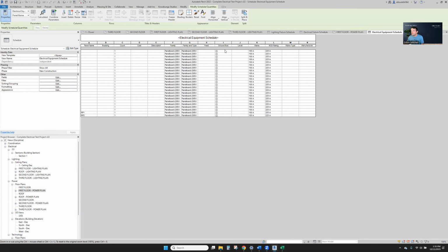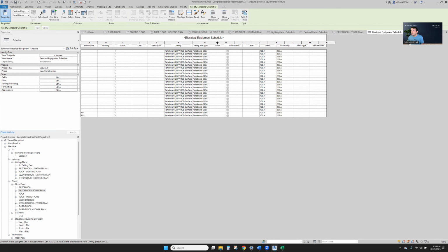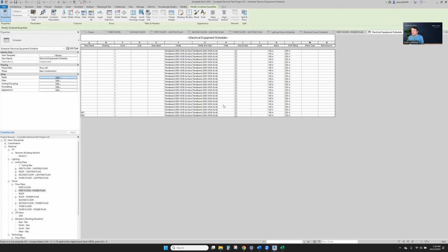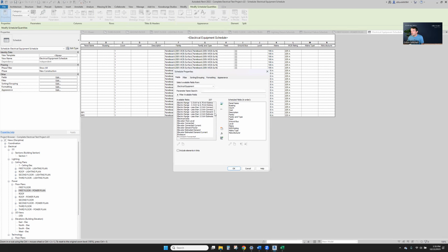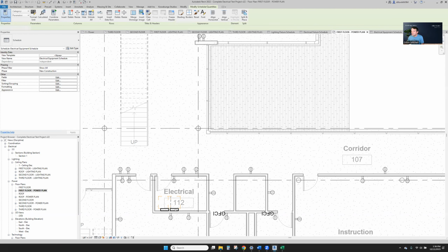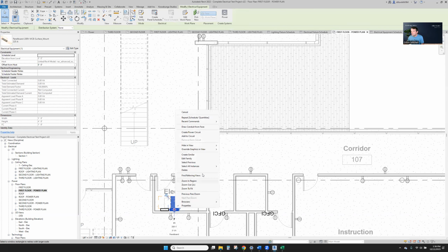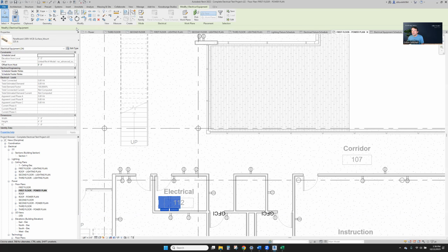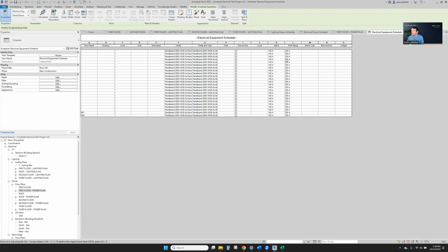There's all these pieces. So we can see, hey, it's a 208 family, right? All that kind of good stuff. We can add voltage if we want. Let's look it up. Voltage, right? None of these are powered yet, so it's going to be 0. But if we go through and select all of these in the entire project, we can look in the distribution schedule.